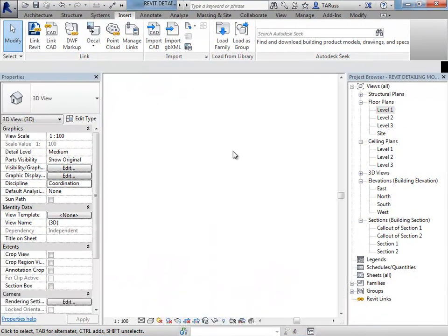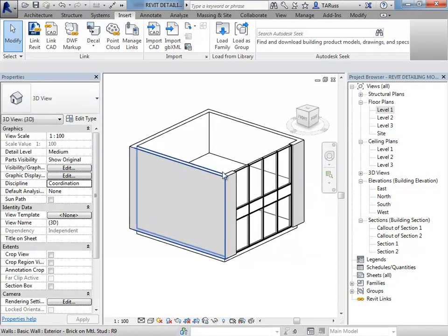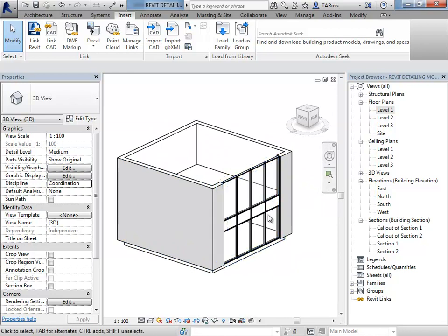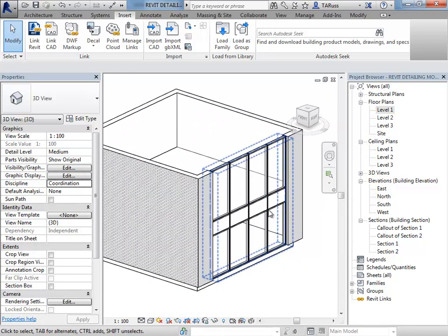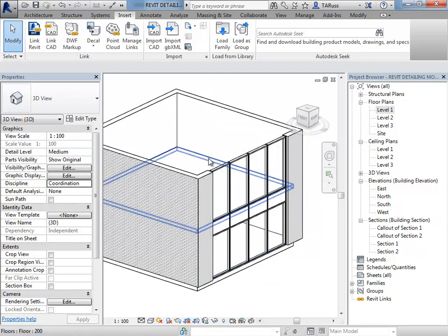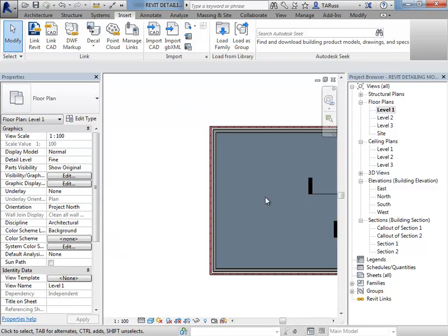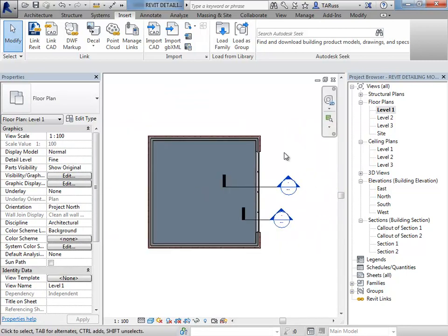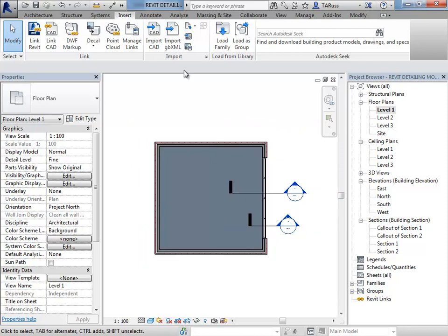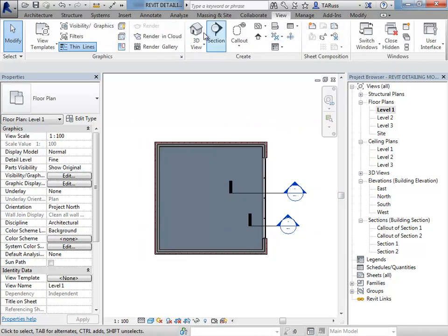So now that that's set up, I'm going to come in here to Revit. And what I've got here is just a basic situation where I've got the curtain wall and I've got 2 floors. So I'm just concerned with the curtain wall here. If you hadn't generated the walls in the back, that's fine. The crucial part is just to have a 2-story curtain wall with a floor plate in the middle, and that's going to simulate that spandrel panel situation. So just to show you in elevation view, or maybe I'll use a section view here to show you what that looks like. I'll just set up a new one here that spans the whole thing.